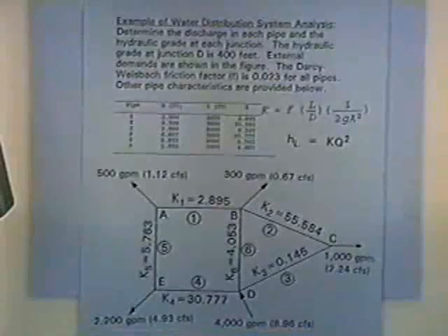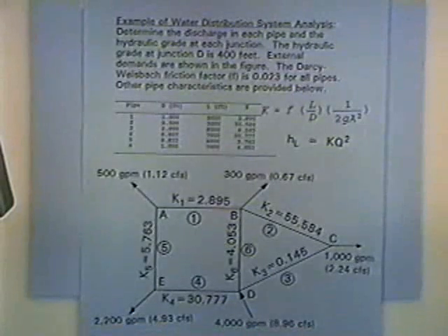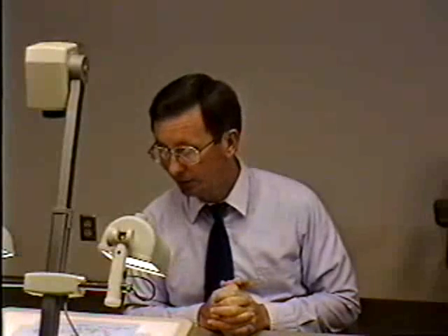As far as the way you would actually handle it, it can be done different ways. A very typical way would be to come up with an equivalent length of pipe. We were talking about equivalent pipes a few minutes ago, and you can just add an equivalent length of pipe for minor losses. That's not unusual, but the system allows for including minor losses as well. Okay.